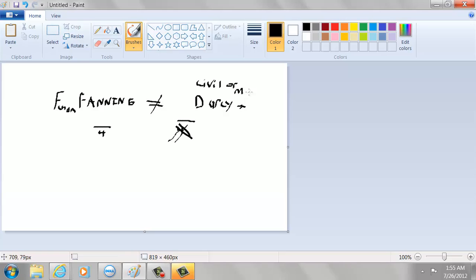If you see a Darcy friction factor, you want to make it Fanning, it's not that difficult to just multiply by 4. It's really not. If you see a Fanning, you want to convert it to a Darcy, all you do is divide by 4. It's very simple, not hard, but important to note that there are differences.